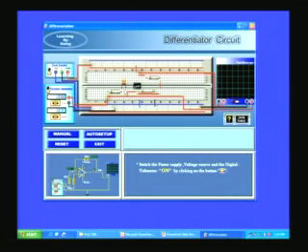So you have 270 ohms in series with a capacitor of 0.01 microfarad, and you have a 10k resistor connected to ground at pin number 3, which is the non-inverting input. You also have a 10k resistor in the feedback between the 2 and 6 terminals of the op amp. So it is exactly the same as what you have here, and that has been wired.